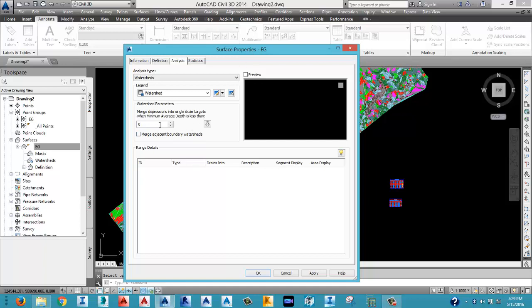Not for drainage design per se, but it gives you an understanding of how the area looks and where the possible direction of water goes. So you definitely use that to design your drainage. Once you have an understanding that the water in this area is flowing in this direction, you don't have to design your drainage to flow in the opposite direction. So that's how this works.